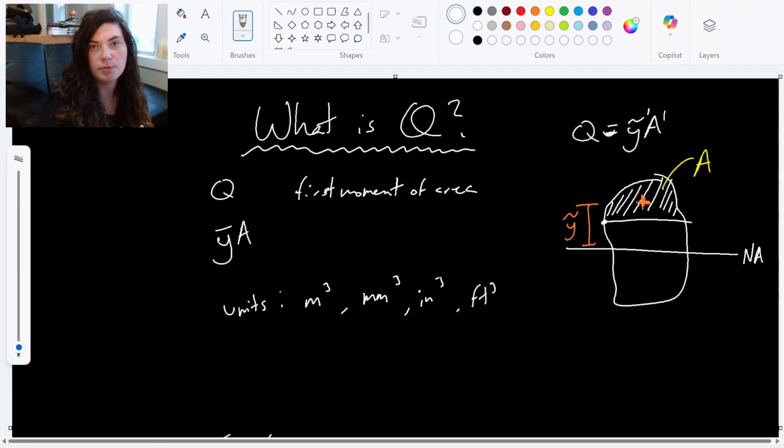It's just a representation of the geometry, just like moment of inertia, even though it has units of inches to the fourth or millimeters to the fourth, it's not actually in the fourth dimension. It's just a property of the geometry. It's just something that we use to get the values that we are actually interested in. It gives us a property value and we say, okay, this represents this geometry.